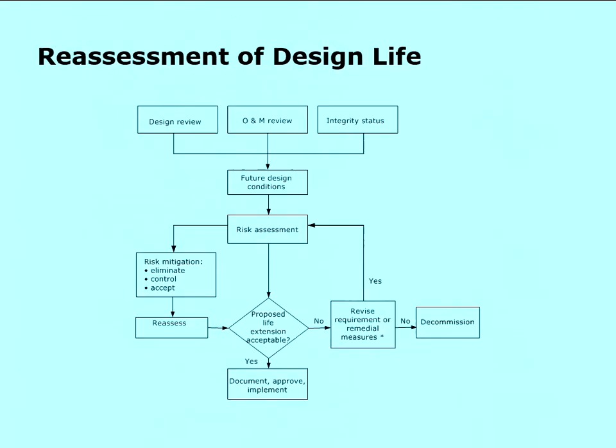Do you know everything about the corrosion in the pipeline? Do you know everything about potential fatigue crack growth in the pipeline? And for things like fatigue, have you actually recorded all the historical cycles accurately enough to do a fatigue analysis? So there are quite a lot of difficulties here. Again, if any of you are looking for any areas of potential research project, then this would be a good one.